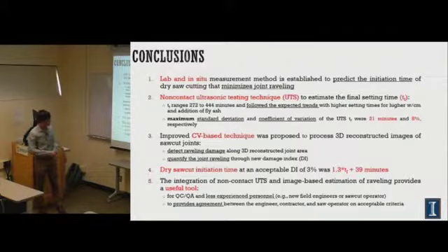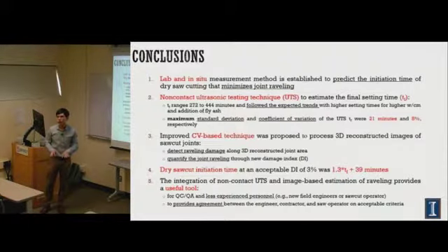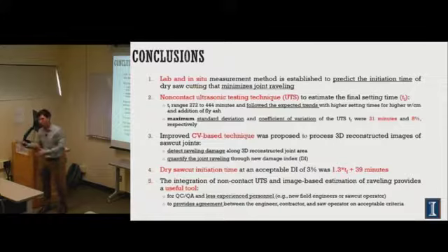And this technique is very useful too for the QA, QC and less experienced personnel to use. So he just needs to present it aside and then predict the setting times and tell the saw operator to commence on the cut.